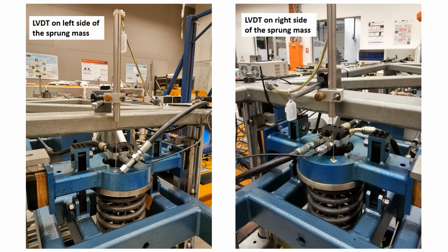Depending upon the type of LVDT, the measurement range of each individual LVDT might be different. So for the scenarios where the mass is added and the spring mass equilibrium point thereby shifts vertically downwards, the body position needs to be adjusted to ensure that the measured displacement during vibration does not result in a maxing out of the measurement range.